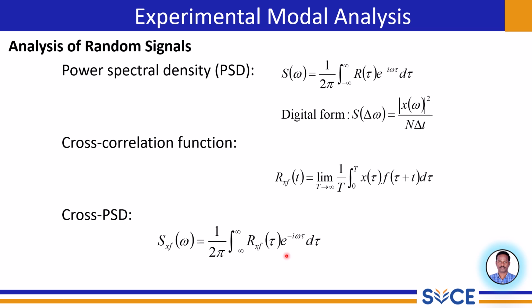In modal analysis, the cross power spectral density between the input force and the output acceleration is fundamental for calculating the frequency response functions.